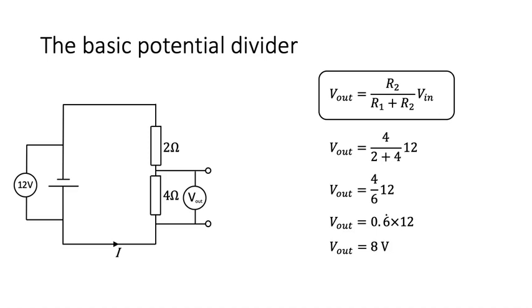So in the last part we just introduced the basic potential divider circuit, which is a great circuit, it's very useful. If you know you're going to have an input voltage of one particular potential difference and you want another one, and if nothing's going to change, if that's just a question of controlling a supply, you don't have maybe much of a choice of what supply you have to be using. But you know you want a particular output for the rest of your circuit, then you can set up a simple potential divider using the two resistors, no problem. But that's not everything it can do.